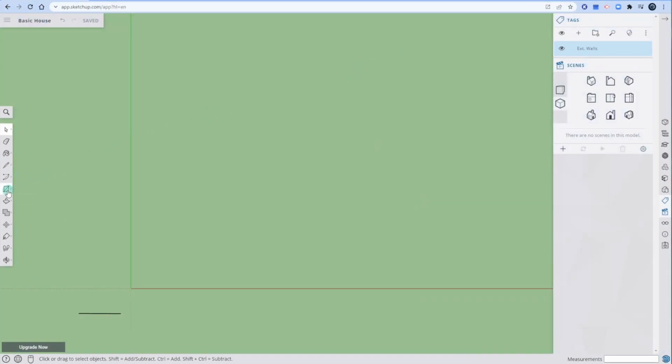On the left side, we have a rectangle, and you'll notice that it's actually starting in the corner of the rectangle. There will be times where it snaps to the center point. Just close your rectangle and choose it again when you want it to be drawn from the corner. And you'll notice I'm also going to start from the origin. It's important to have the origin as part of your drawing and 3D modeling, just so you have an orientation to go back to when you want to look at views and stuff.